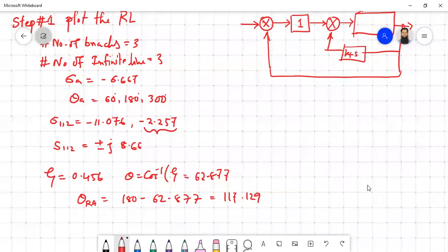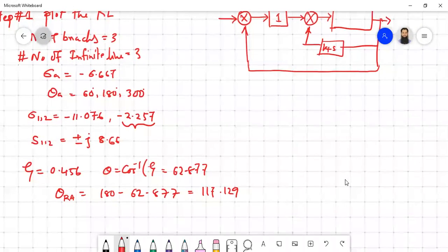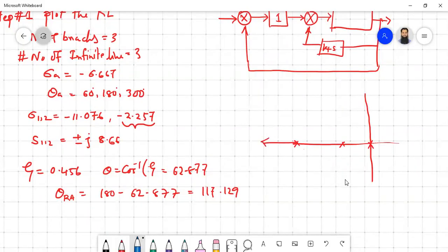Okay, so all these are actually for finding your root locus, the tentative root locus. So we know what the root locus will look like. So you'll have poles at 0, at 5, at 15. So basically the 15 will be going in that direction. So this will be merging in between 5 and 0. So that is why we actually pick this value. Okay, so they'll be merging, then they will have a curve like this, something like this.